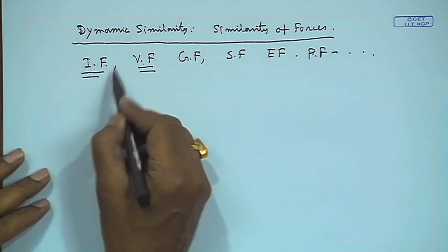Usually we deal with the velocity, pressure, density, viscosity, the fluid property or the characteristic geometrical dimensions of the problem. So, therefore, it is customary to express these ratios of forces in terms of those variables concerned with the fluid flow problems. So, this is done by scaling the forces.